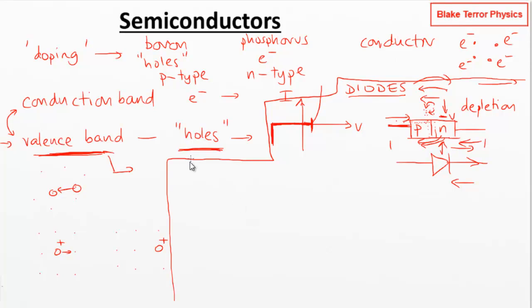Now, LEDs, light emitting diodes, is this sort of setup, but you're constructing the diode so that when these electrons start filling in the holes, as in we've got movement into valence band holes, that combination, that movement to a more stable state, as in a decrease, we're going to a more bound state.